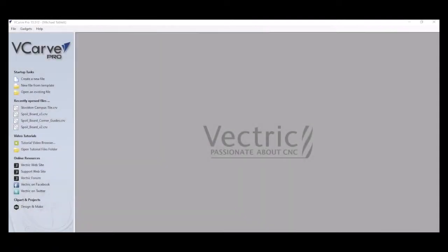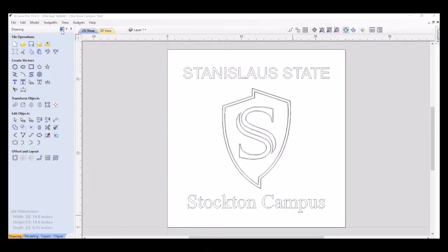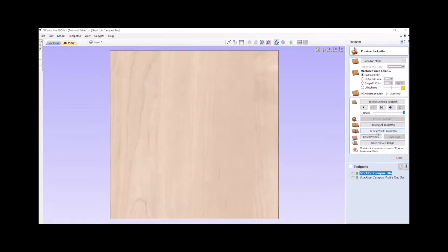To start, we need to create our design in CAD/CAM software. We will first create our design in the CAD, Computer-Aided Design side of our software. Now that our design is complete, we will move to the CAM, Computer-Aided Manufacturing side of the software. This is where we will create our toolpath. The toolpath is a set of instructions the computer will send to the CNC control board, which instructs the stepper motors on which direction to move.